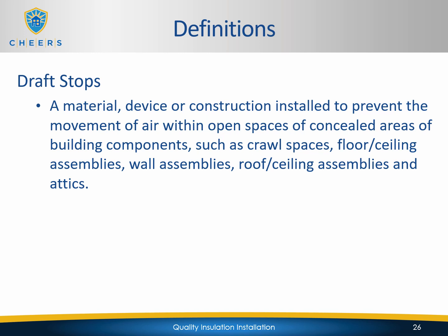Draft stops. A material, device, or construction installed to prevent the movement of air within open spaces of concealed areas of building components, such as crawl spaces, floor ceiling assemblies, wall assemblies, roof ceiling assemblies, and attics. So draft stops limit air movement within the actual building assemblies.